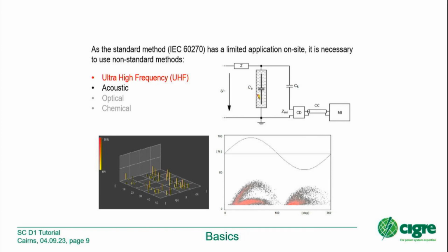No answer, no signals for voids, etc. From my experience, when I was with Siemens in former times, we had the knowledge about acoustic PD measurement. We were trained on that, but we applied it in, let's say, 1% of all cases for measurement. So it's an available technology, it can be used, but with limited output.